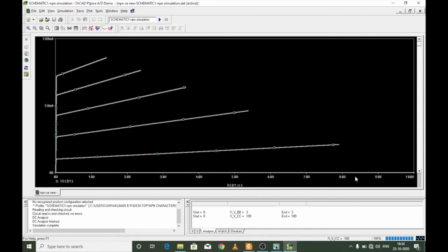When the base current is sufficient enough to drive the base to emitter junction to forward bias, we will start to obtain these characteristic curves above the x-axis, so that now the collector to base junction is reverse biased while the base to emitter junction is forward biased. Right? So the characteristic curve will move upwards as the value of the base current is increased.